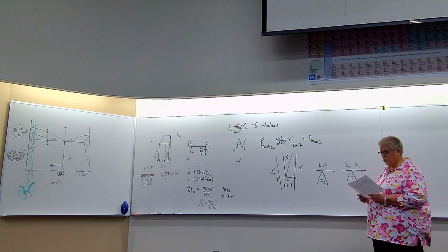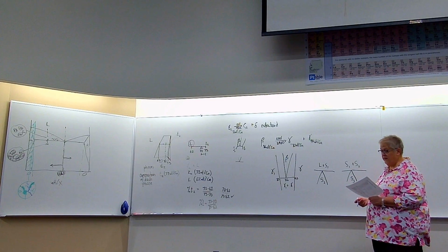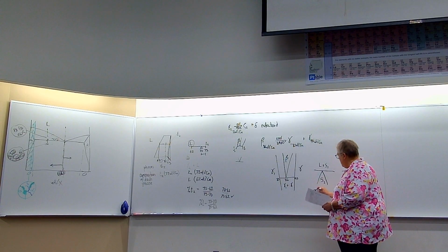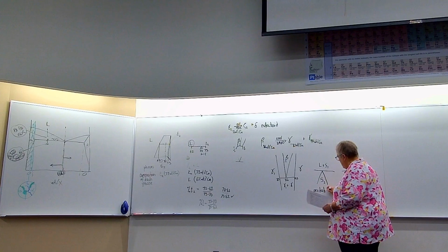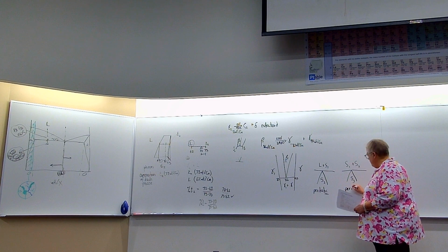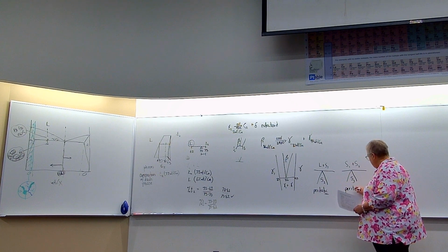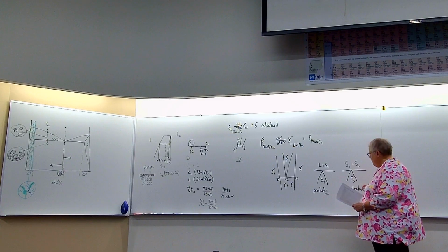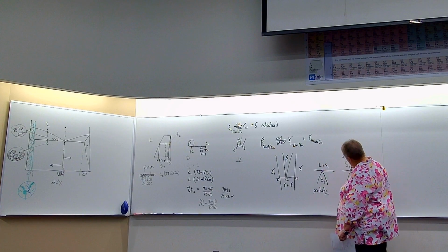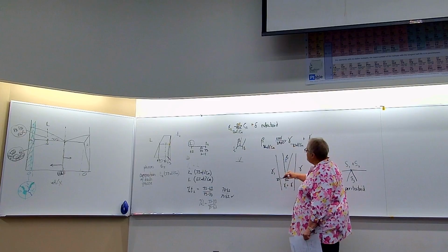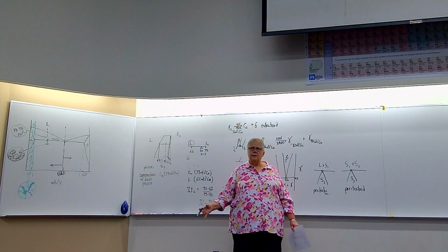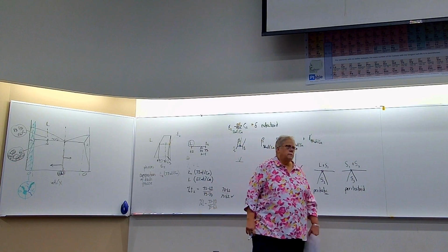So there's a lot of those. If you look, you see a lot of upside down V's. Those are all eutectics or eutectoid or peritectic. If it's a tick, that means there's a liquid. And peritectoid. You don't need to remember that. I'm just pointing it out in case you see those and you're like, I wonder what those are. Because what's unique about each of these points is that it's a place where 3 phases can be all at one time together. Okay?